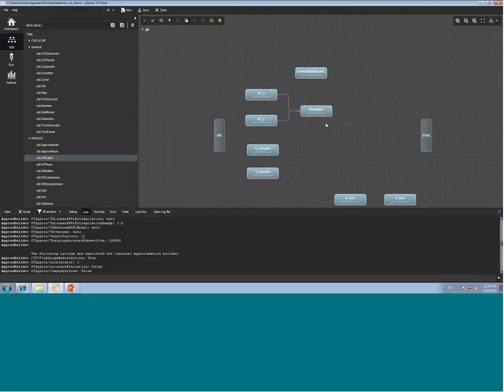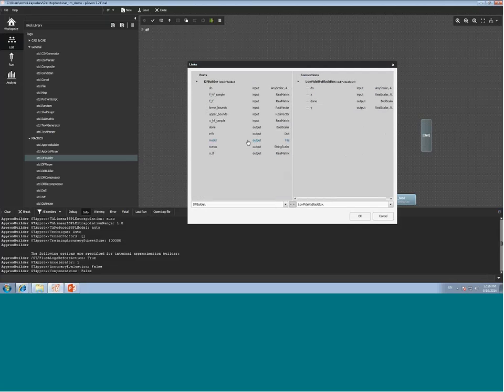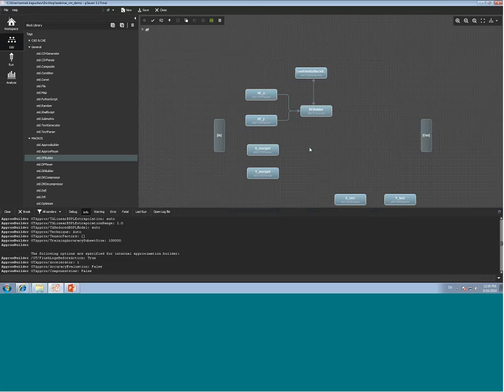And now we have to connect the black box. The black box should provide outputs to the data fusion builder. They go to the F low fidelity input port. We should also make the reverse connection, as the data fusion builder provides the input sample for the low fidelity, and we should connect the XLF output port with the X input port of the low fidelity black box.